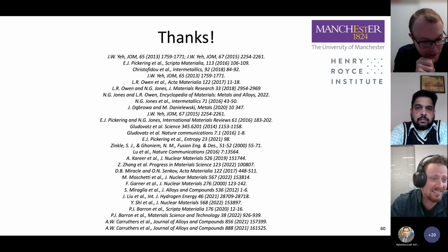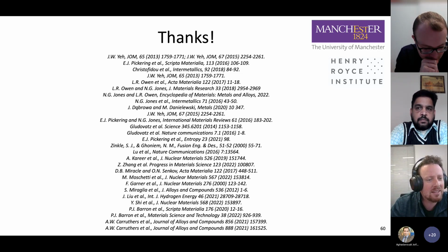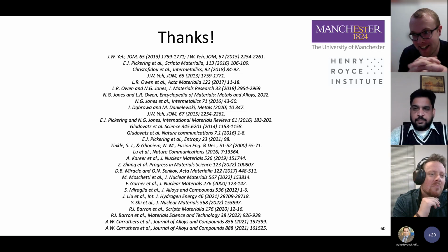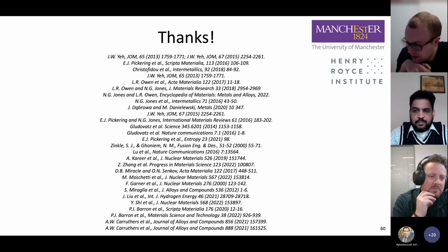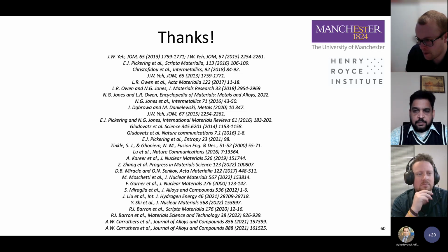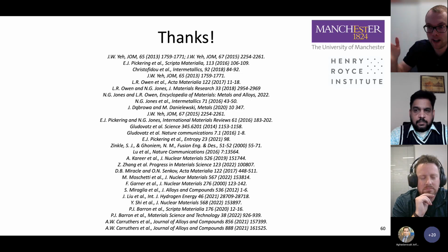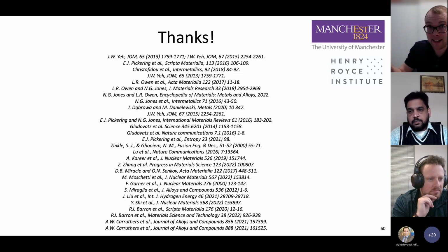I don't know. I think I may have heard someone else talk about that before. But the idea of taking all the stuff you can't recycle normally and just creating HEAs with it is a really interesting idea. Nothing really springs to mind in terms of a high-entropy alloy that is cheap. I can't think of one really, because nothing's cheaper than iron in general, and as soon as you start adding more elements in, you tend to just add in more expensive elements.